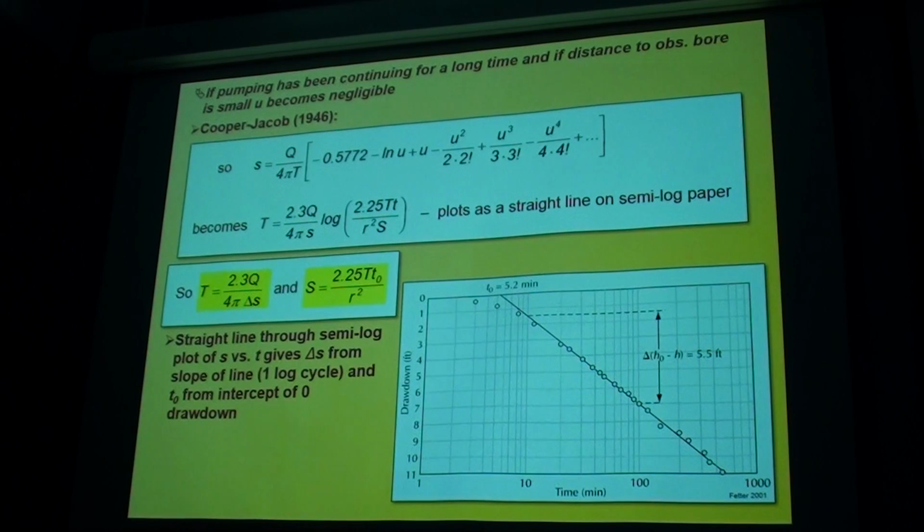Again, your computer will show you this. You put the line of best fit through. You've already programmed your data in. There's no type curve this time. This is your data. This is the log scale for your time, but a linear scale for your drawdown, for your s. And you can put a best fit line through that. You can get the slope of that best fit line.